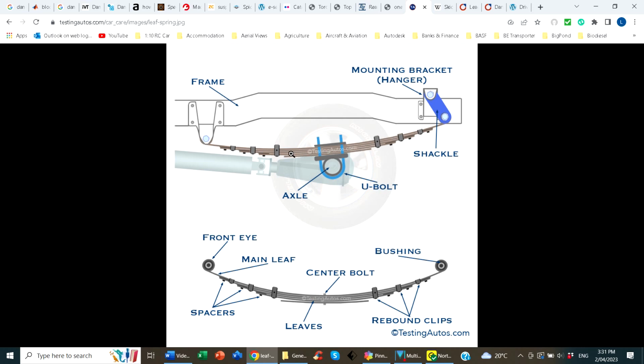Generally speaking, leaf springs are not well designed. They're very simple, therefore cheap. If you're going to use them on heavy weights, you end up with a lot of leaves, and that makes them very stiff and therefore not very good at going over bumps. But done right, for lighter loads, they can be a very simple, good, cheap solution.